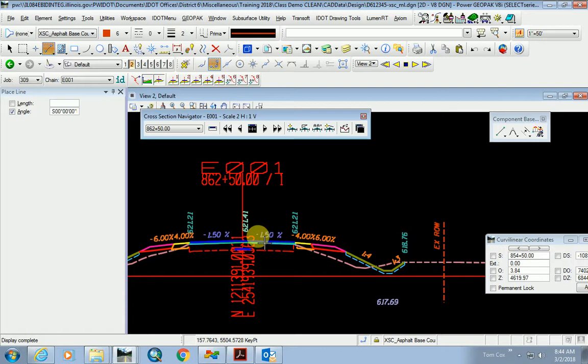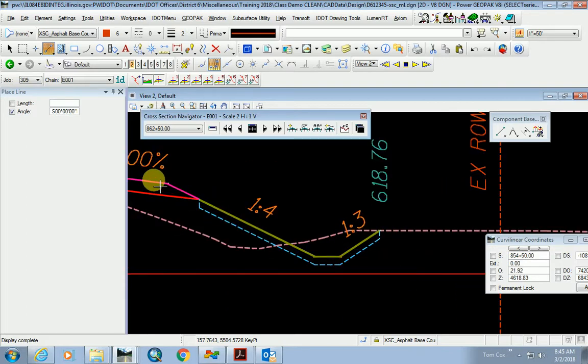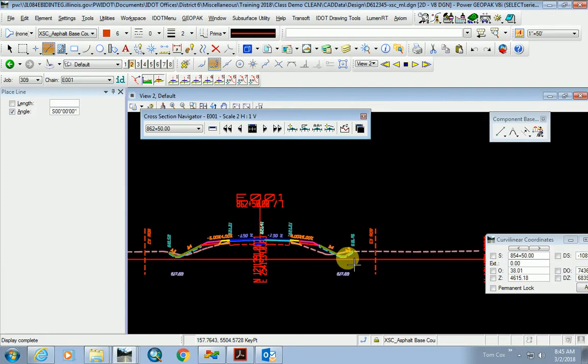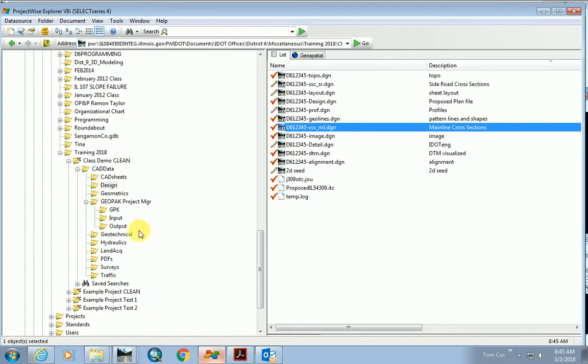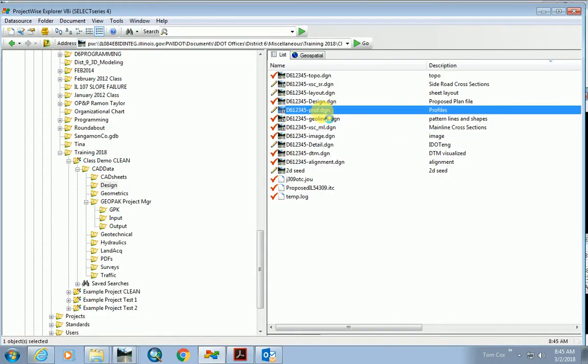And then once I did that, I would delete everything here and keep the existing, it's locked down. Then I would type in the name of that special ditch profile in that redefinable variable and just hit run. It'll reprocess again, and then this ditch bottom, rather than being 3 feet deep, would be the depth of my profile at that location. So yeah, let's go back to profile for a minute.